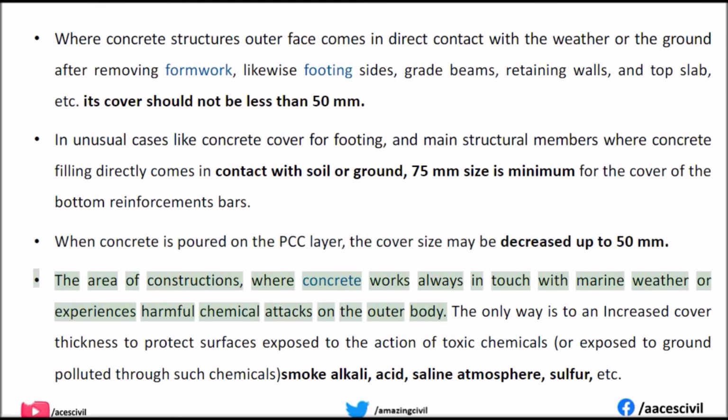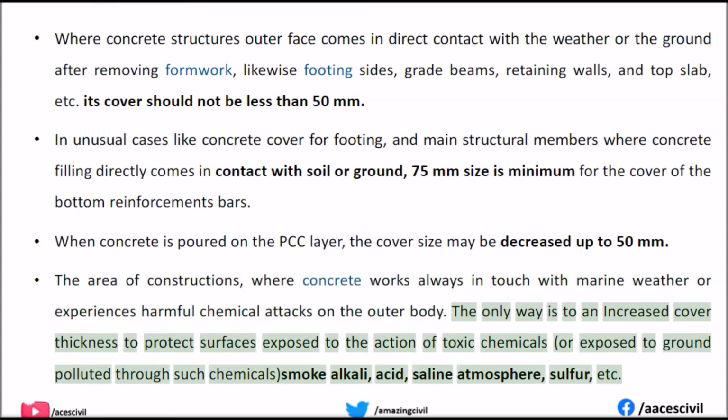In areas of construction where concrete is always in touch with marine weather or experiences harmful chemical attacks on the outer body, the only way is to increase the cover thickness to protect surfaces exposed to the action of toxic chemicals, or exposed to ground polluted by such chemicals, smoke, alkali, acid, saline atmosphere, sulfur, etc.